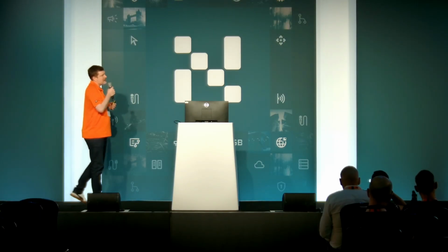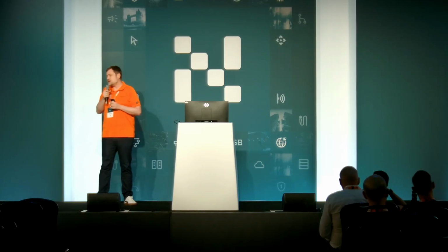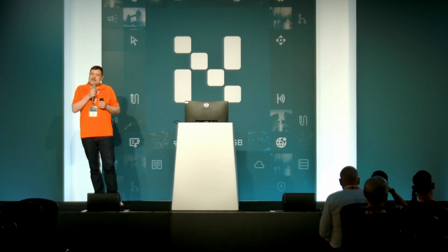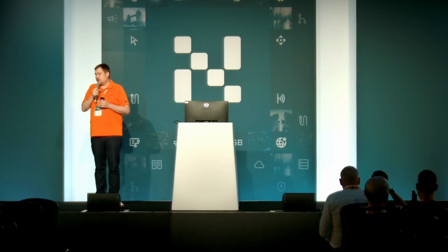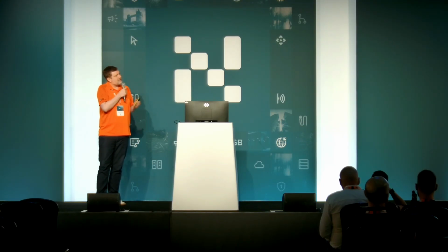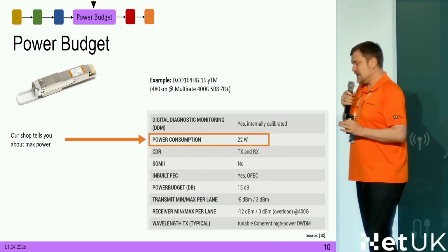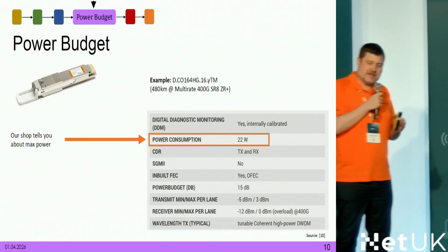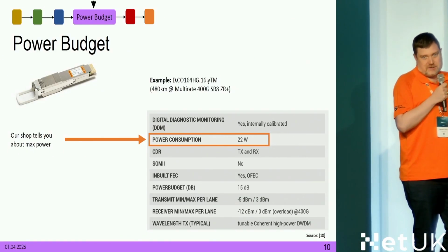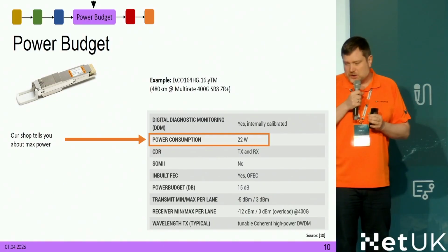Now when you plan your power budget, you need to buy transceivers, and before you buy them, it is good to look up on the page of your supplier what the maximum power will be. You usually see power consumption, not always sure if it's a good word or if it's clear, but it's the same value. It is the value of what the transceiver will consume at most.